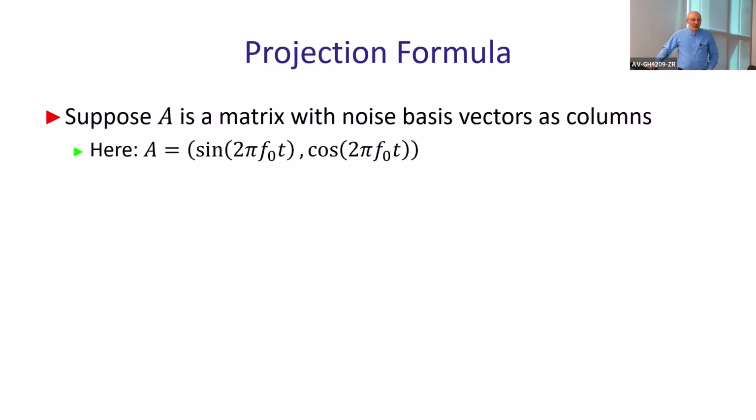Yeah, so Fourier transform gives you the entire spectrum of the signal, which means the distribution of all possible frequencies on a continuous scale, so for each frequency you'll have a particular magnitude and phase angle. Here you know that you have only one sine wave with one phase and one frequency. You don't need Fourier transform in that case because you know particularly what your noise is. Typically people use Fourier because they don't know the spectrum of the noise or of their signal, and they go the other way around because they know more about signals than about noise. So in most cases, you don't know what your noise is.